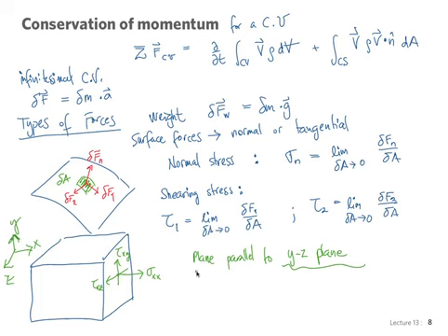So in this, the normal stress, we have these three stresses, sigma xx, tau xy, and tau xz. And you notice that the first subscript is always x. This is going to be our notation because on the YZ plane, the normal vector points in the x. So the first subscript refers to the direction of the normal on that face. All of those first x's.